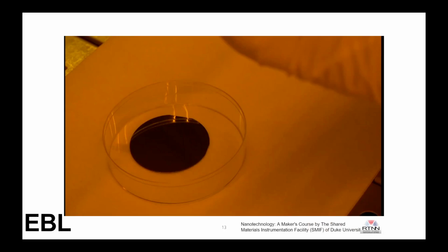Like that, if we are using silicon, this is my silicon wafer. If you want to heat it, from either chrome or platinum you have to deposit that material and you have to design the heater in that design area. Then you have to apply some voltage or current here. With the voltage and current that material will be heating and it will work as a heater. On the bottom or the surrounding you can design your heater.